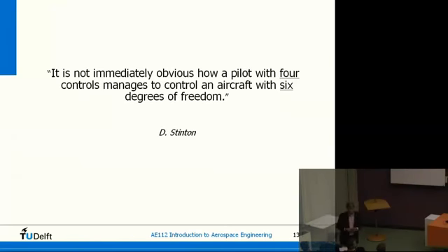Is that something that happens during the crosswind landing? Yes, during the crosswind landing, you want to slip on purpose because you want to align the nose with the direction of the runway for the wheels, while aerodynamically, if you have a crosswind, you need to steer up with a drift angle, basically, to make the aircraft go straight ahead. So then you need to slip, but to avoid going sideways, then you also need to roll to compensate that again. But this is way too complex. We're first going to look at a longitudinal static stability as an example. And the lateral cases are quite complex. You have side slips, drifts, controlled turns or slipping turns. That's a bit too much to deal with mathematically today.